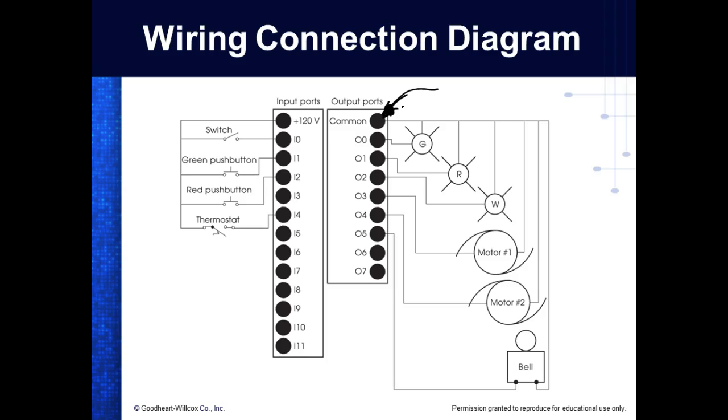So this makes sense? Now normally we don't run motors off the PLC, unless they're little tiny motors, maybe a fan motor, something like that. What we normally do is we'll come over here and we'll have a relay. And I've showed y'all relays, right? What's the advantage of a relay? What can we do with a relay? We can take a low voltage to control a what? High voltage or even high currents. So a lot of times we'll use that.